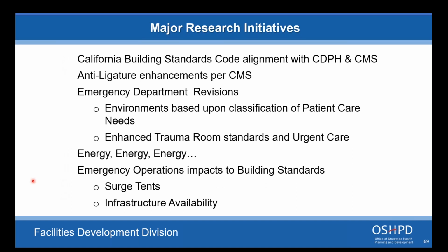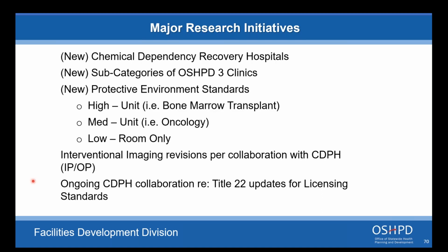One of the things we're finding is that the oxygen piping that is installed in hospitals was not designed for constant use by everyone at the same time. So if they have a lot of respirators going continuously, we're concerned there might be some bottlenecking going on there. So we're looking at that as well.